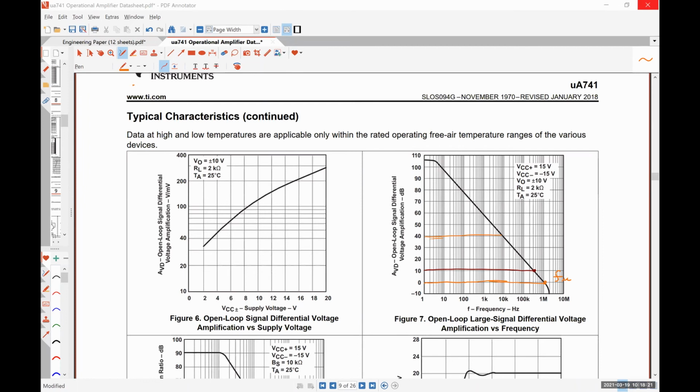So this simulation is exactly showing you what you observe in your 229 lab. The bandwidth of a real op-amp circuit is finite. And if the gain bandwidth product of your desired system is larger than the gain bandwidth product of your actual op-amp, you will not be able to achieve the gain you're looking for. All right, so the next thing that we are going to talk about, unless there are any other questions, is the slew rate.